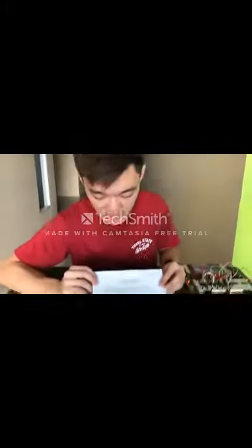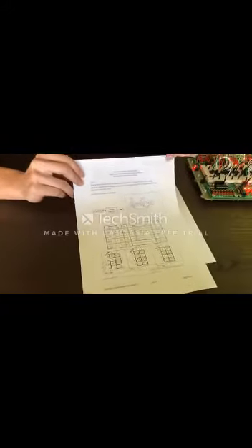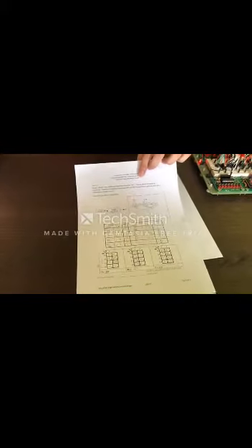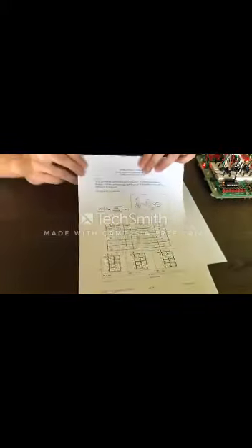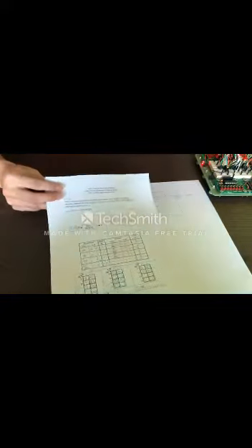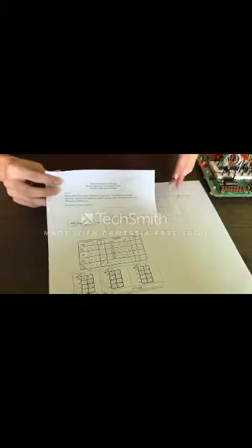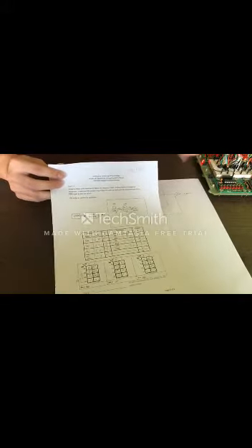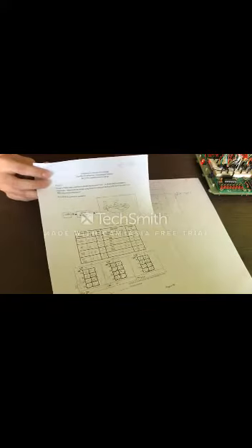For this part of the experiment, we designed a Mealy state machine to detect the sequence 011. This machine will detect overlapping sequences also. We implement the design from part 2 by adding a state machine using D-type flip-flops, a few NAND gates and an XOR gate to test the circuit.